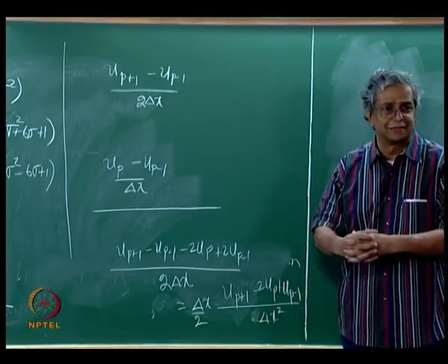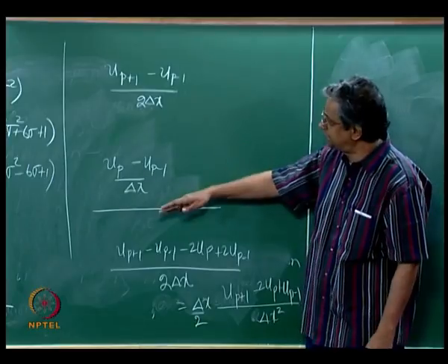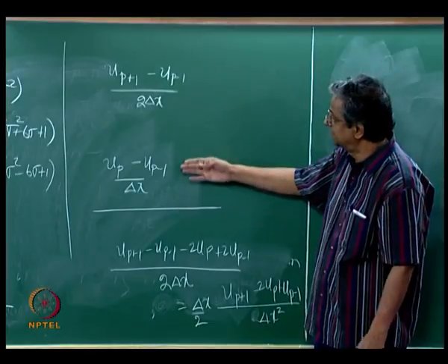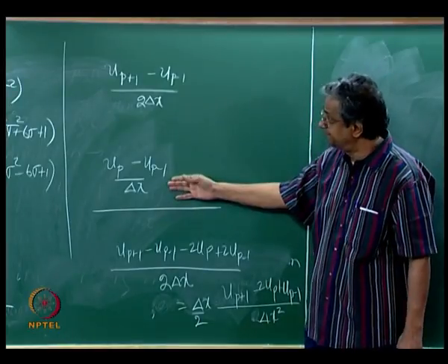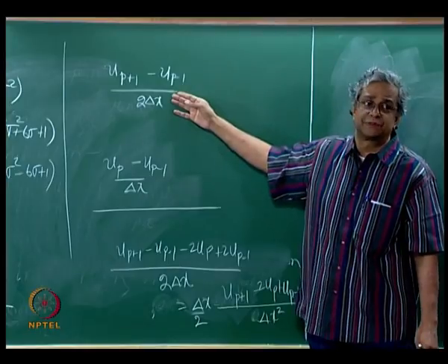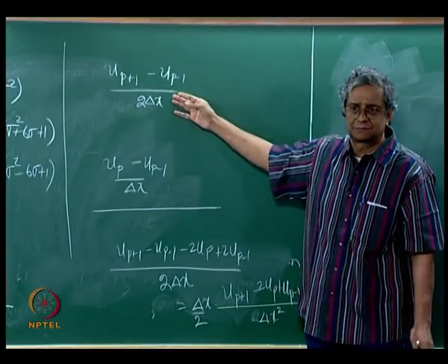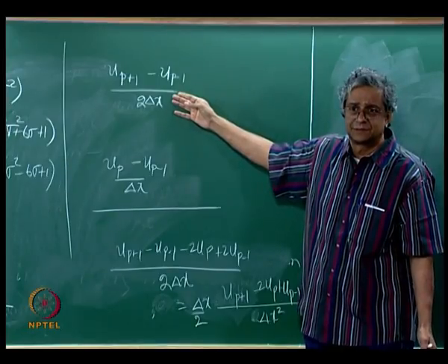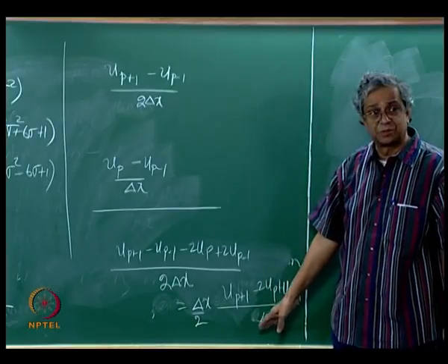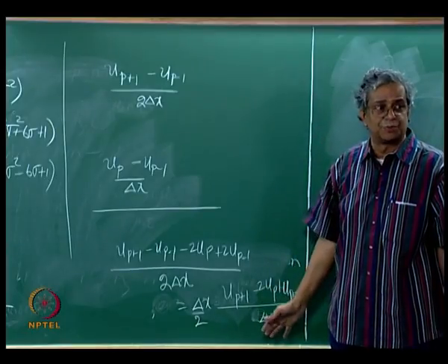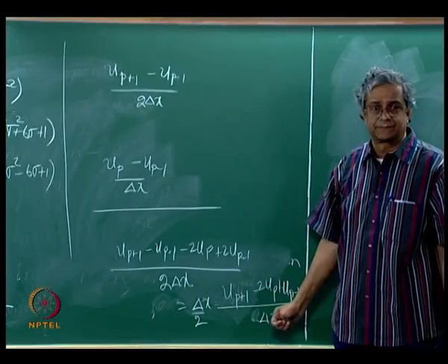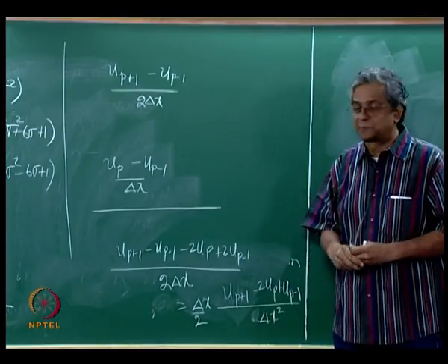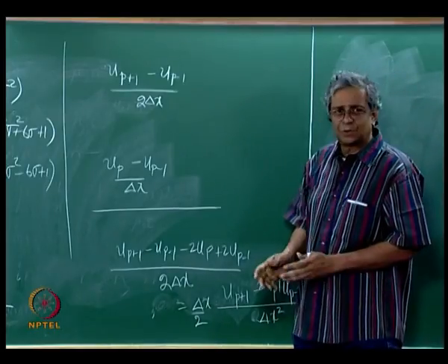So this sort of brings a little closure here. So the difference between the modified equations and the difference between what we are doing here, between central differences and forward and backward differences, if you are doing upwinding, what you are effectively doing is you have taken central differences and added some kind of dissipation, okay. This is the exact amount of dissipation that you have added, which caused a change to your modified equation. Is that fine, right.